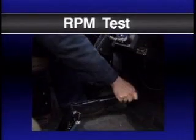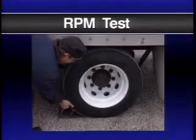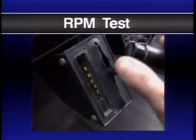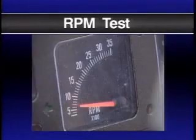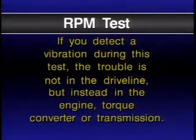First, do an RPM test. Set the vehicle parking brake. Chock the wheels. Put the transmission in neutral and start the engine. Run the engine through its RPM range from idle to no load speed. If you detect a vibration during this test, the trouble is not in the driveline, but instead in the engine, torque converter, or transmission.